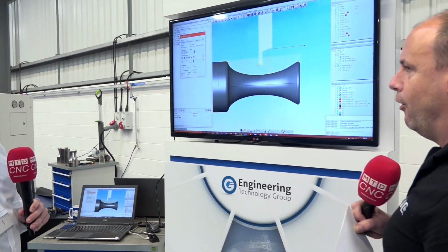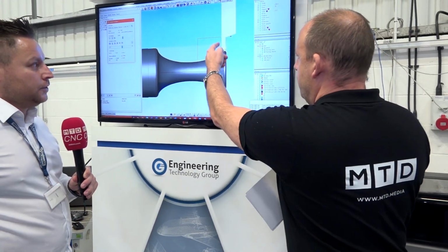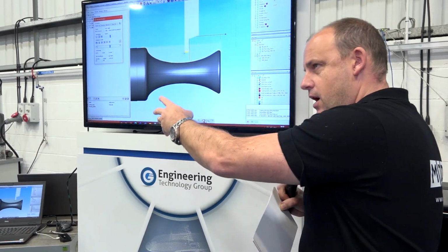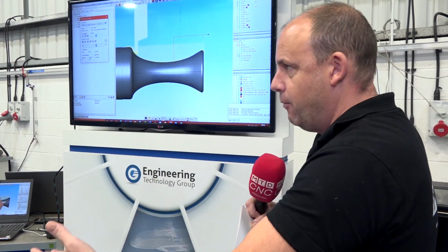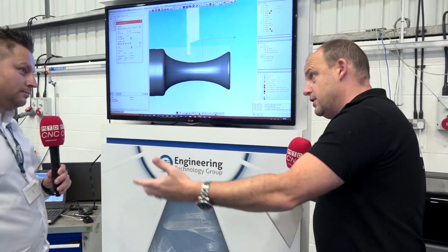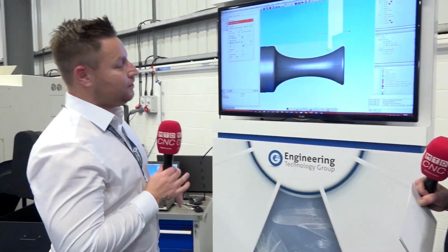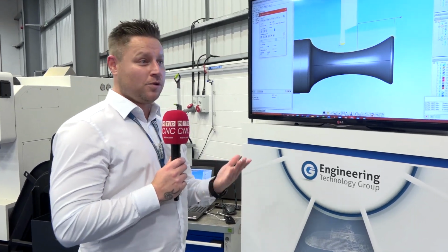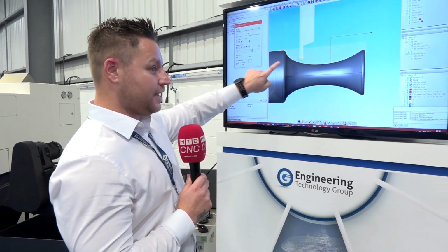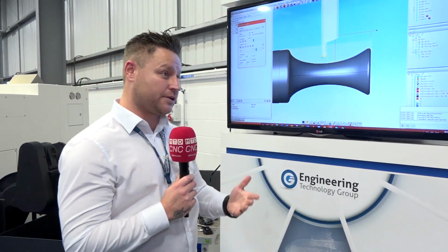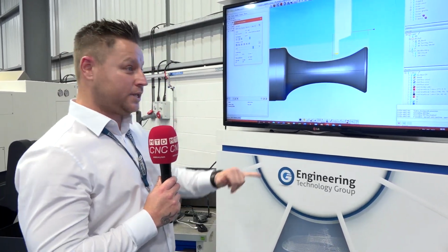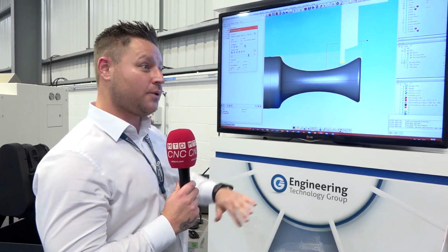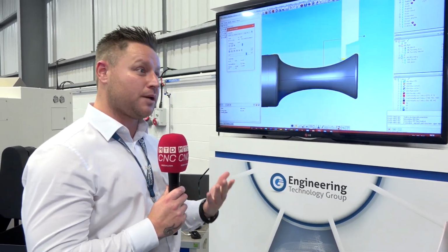And what about the wear on this insert then? It looks like we're very focused in certain areas. Obviously that will mean those areas will wear faster than the other areas of the tool. Not necessarily. Again, this is where the infeed factor comes into play. Your normal cut would be, for example, a 1.2 depth of cut. Now I'm getting into dense areas, so the infeed factor will decrease. Instead of a 1.2 depth in the condensed areas, it will adjust to maybe 0.8 or 0.6 or even less.